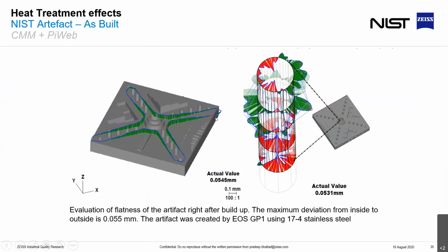On the as-printed part after depowdering, we are just measuring this part, still on the build plate as built. You look at the flatness of this contour and the cylindricity of the hole right in the middle. If the part has a tolerance of about 50 microns, this part is just barely in tolerance, with about 54 microns and 53 microns total deviation.